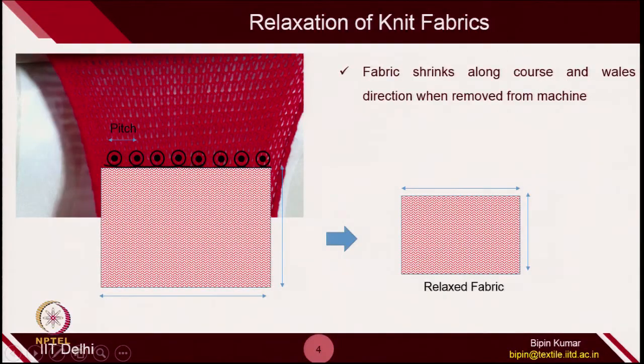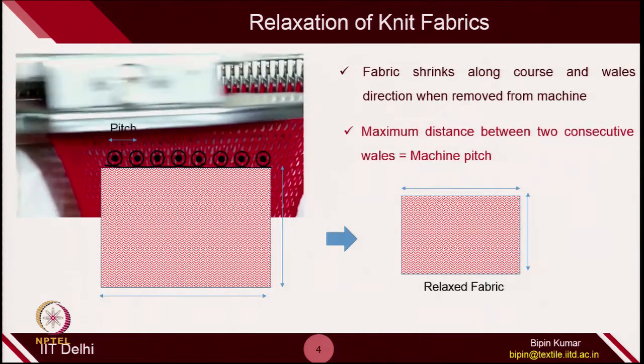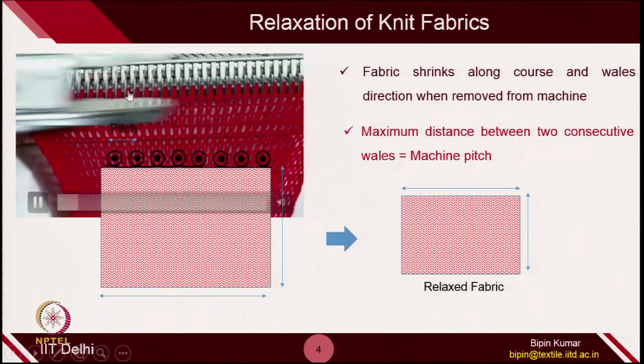Fabrics shrink both in course direction and wale direction, and in this lecture we will try to understand why, how much the fabric will shrink, how it relates with the stitches, and how the tuck, float and loop control the shrinkage.